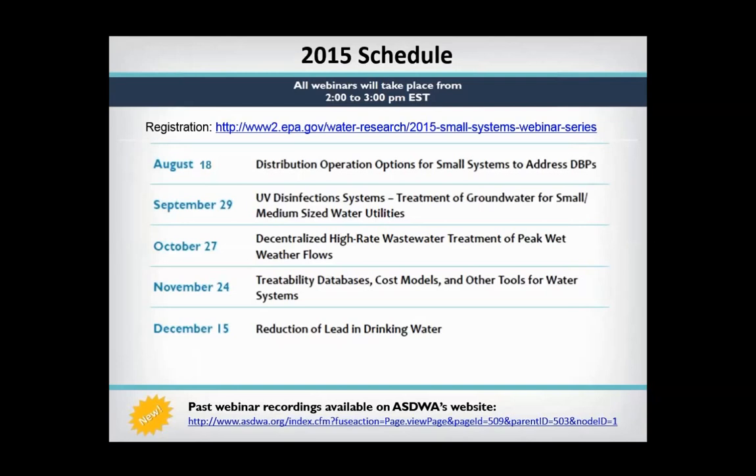But I don't think it's wise to just say we've had a history of compliance, we're just going to forget these entirely, because construction within a home or in the system can kick up scour in the pipes and knock loose some of the scale and cause spikes in your samples. So I don't think it's the best idea to say, okay, these guys are out just because they've been compliant for a long time.